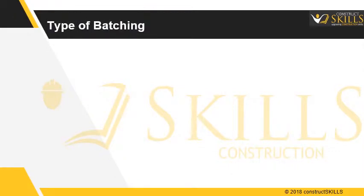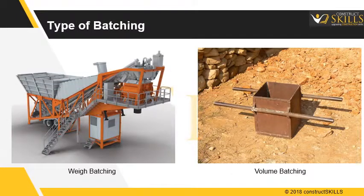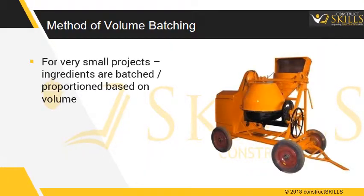Two common methods of batching are volumetric, as in case of nominal mixing, and weight batching, in case of design mixing. For all important concrete work, batching should be done by weight, and mixing by machine mixers. For very small projects, where mixing is performed on the site, the materials are usually batched by volume.